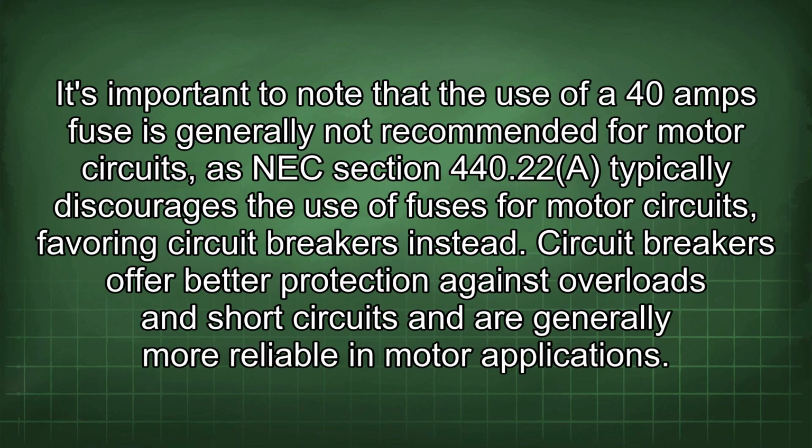It's important to note that the use of a 40 amp fuse is generally not recommended for motor circuits, as NEC Section 440.22 typically discourages the use of fuses for motor circuits, favoring circuit breakers instead. Circuit breakers offer better protection against overloads and short circuits and are generally more reliable in motor applications.